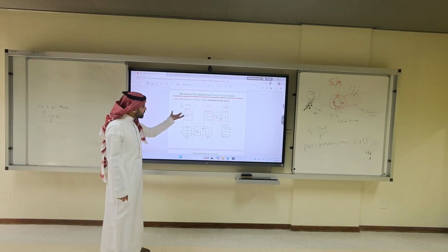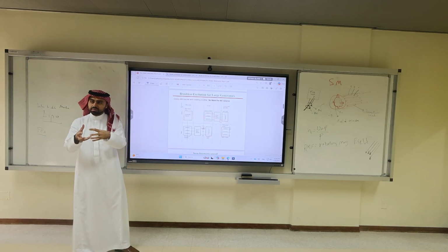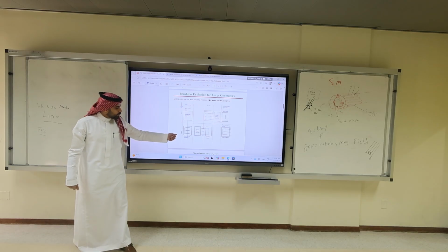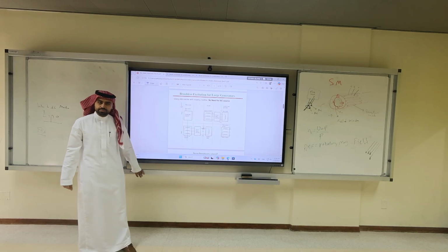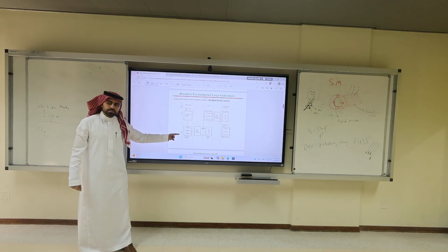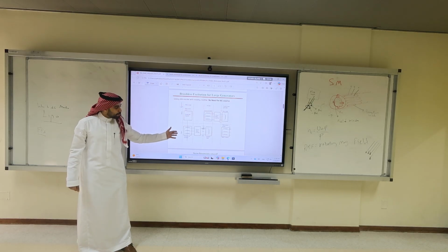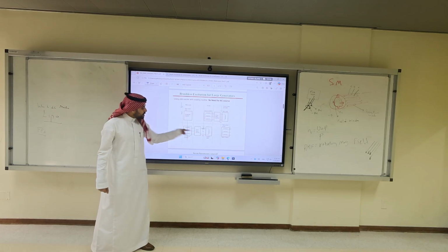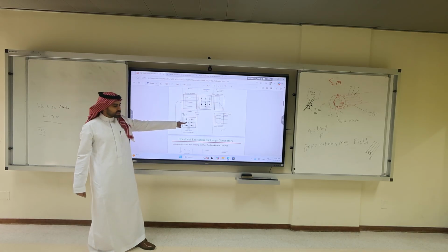If I rotate the permanent magnet on the rotor, I'm going to induce small three-phase on the stator. A group of conductors, we call them pilot exciter armature. Then I have the small three-phase AC. I put it into a rectifier. So this rectifier is actually this rectifier.